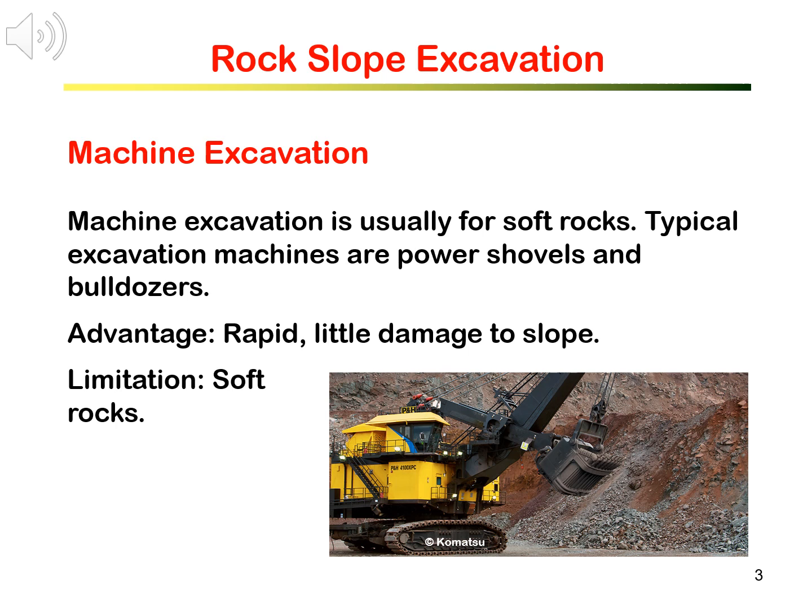Machines can dig and remove the ground rapidly, and they can excavate the ground to form a slope exactly and cause minimum damage to the slope. The limitation is that those excavation machines can only excavate ground that is relatively soft and weak. If the ground has hard rocks, the machine will be damaged.